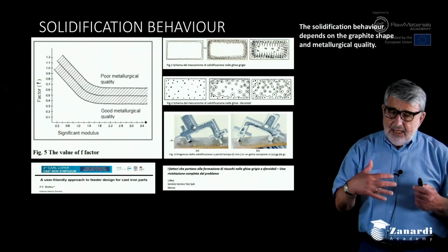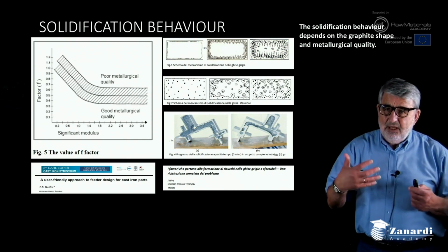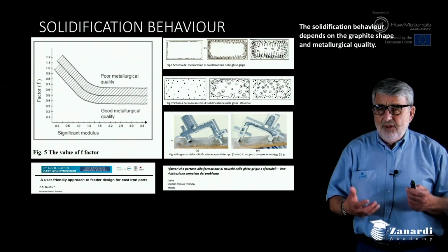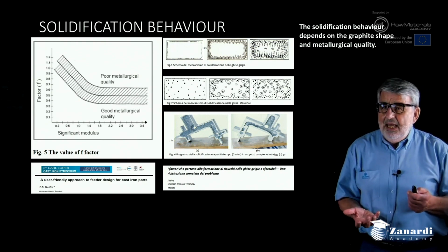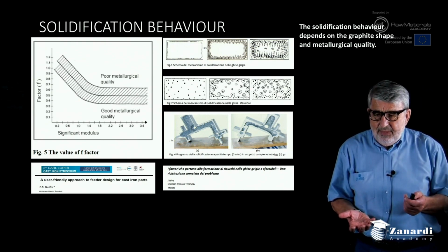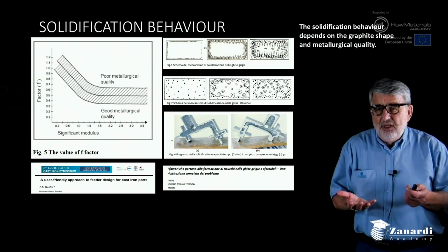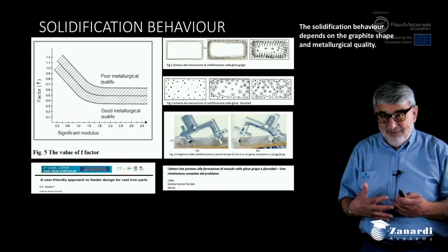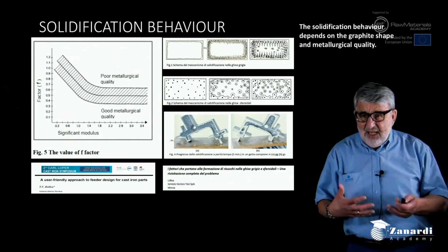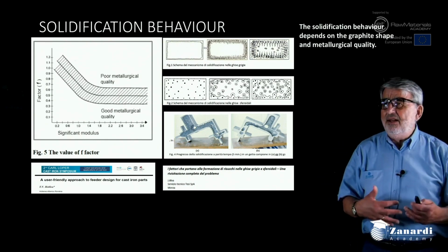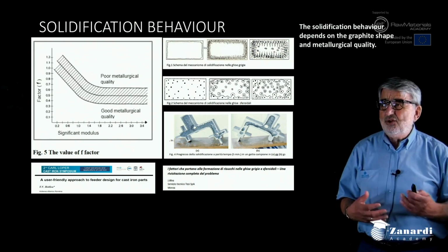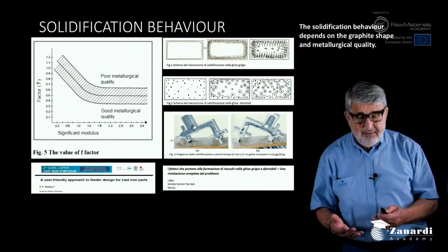It means that each time the lamellae are growing because of carbon deposit, we have expansion of graphite into the melt that helps the self-feeding. So feeding a lamellar graphite iron is typically easy, and it is easy to get sound casting.